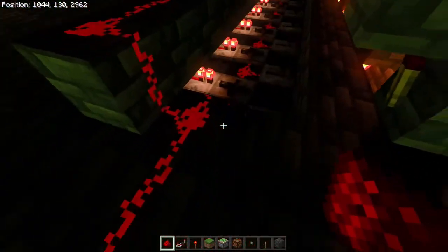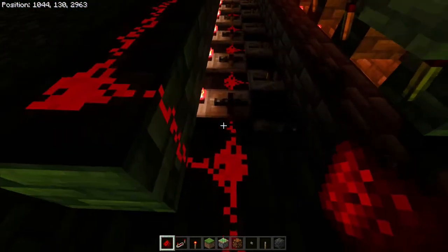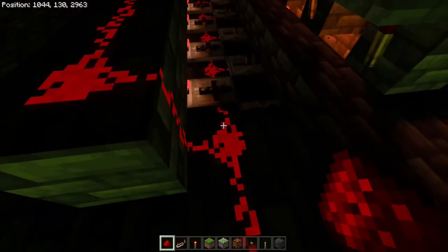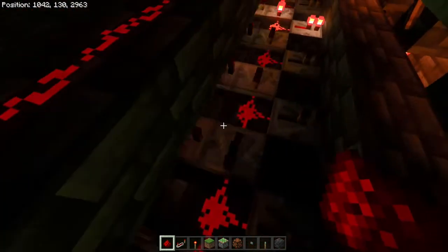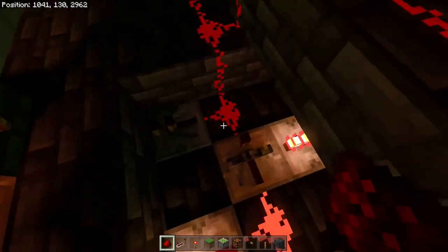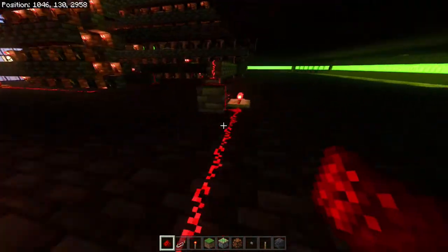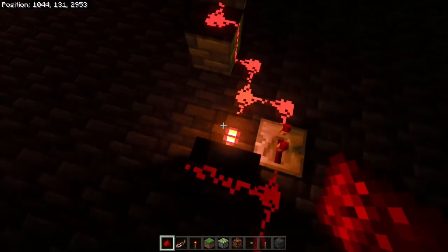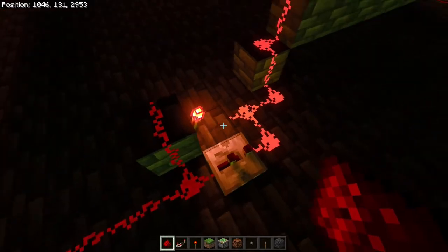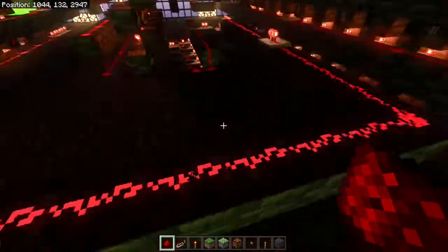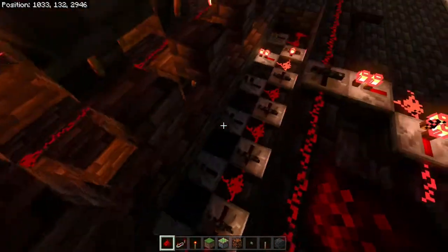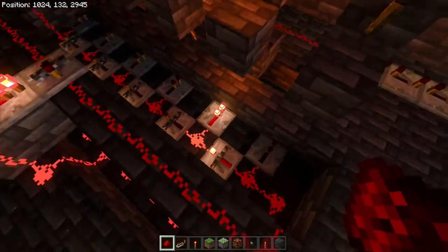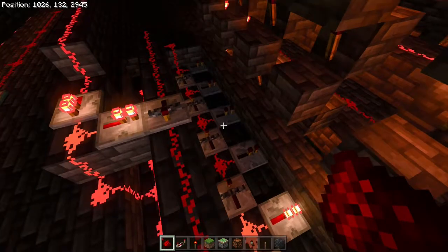And then this part here, this will turn on when we're going between 0 and 1. I guess when we first go to 0 is when this will be on. And then that goes through. This is another rising edge filter. And then it comes around here and clocks this 6-state machine, which is the 10 minutes state.